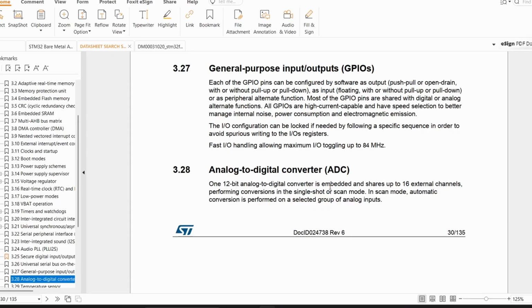Okay, now if you map it to 3.3 volts and calculate, you will get what voltage will correspond to what value. So if 0 volt gives you 0, right, and 3.3 volt gives you 4095, then half of 4095 comes to 2048. So we'll get half of the voltage also, like 1.65 will be the voltage value.